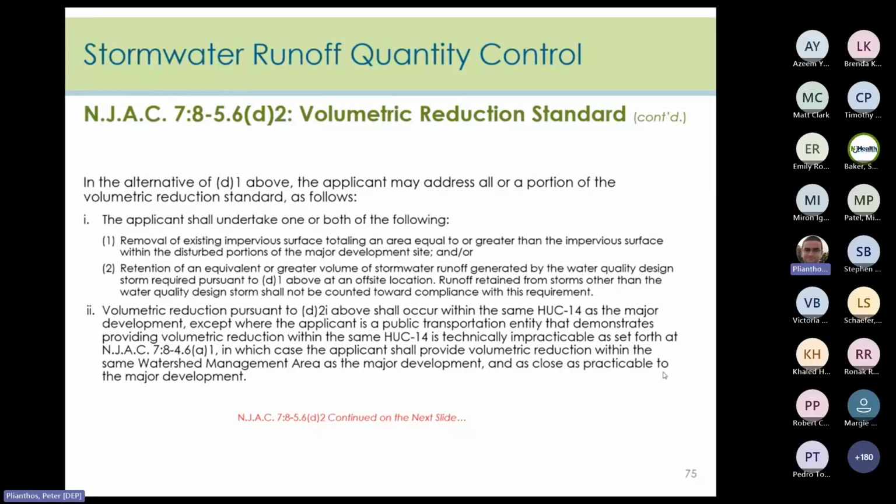Or the second option is off-site retention of stormwater. Alternatively, or in addition to removing impervious surfaces, the applicant can retain an equivalent or greater volume of stormwater runoff generated by the water quality design storm at an off-site location. It's important to note that runoff retained from storms other than the water quality design storm does not count toward meeting this requirement.